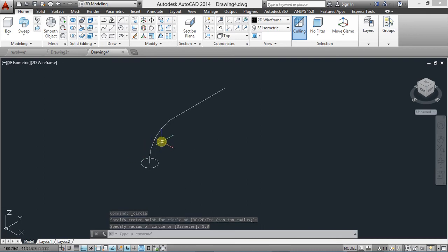I want us to duplicate this as many times, up to 6 places, because we are going to use several sweep styles. Okay, we will use normal sweep, and we use sweep with scale. We use sweep with twist and different types of sweep and with different types of sketch profile.